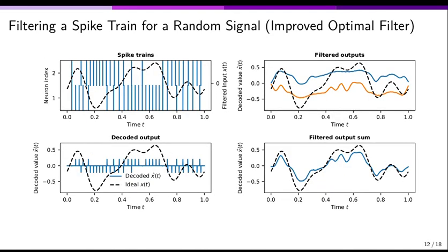We're still going to have a little bit of a problem, especially if you start really playing with your signal, and you have a big mismatch between what it was trained on and what you actually tested on. If you train it on high frequency signals and test it on low frequency signals, you're going to have issues. But we can definitely find this optimal linear filter.